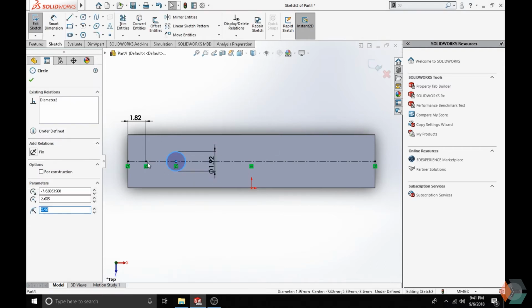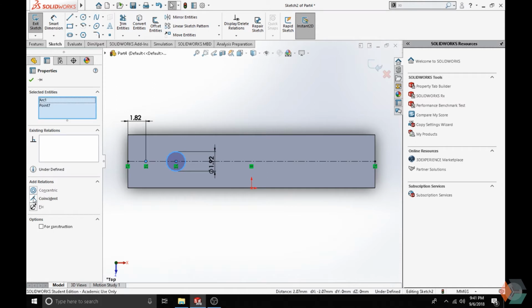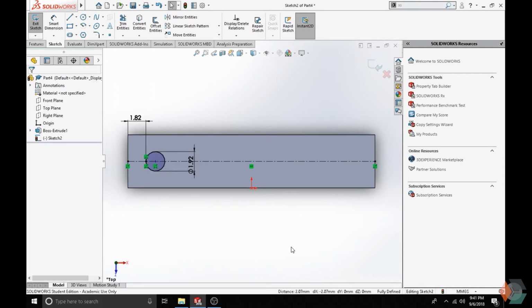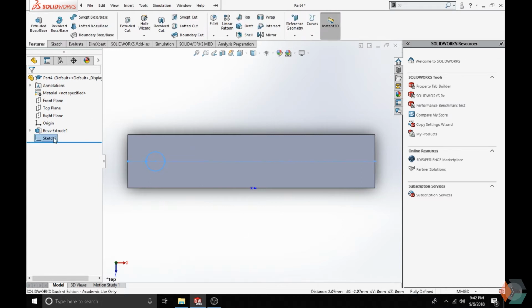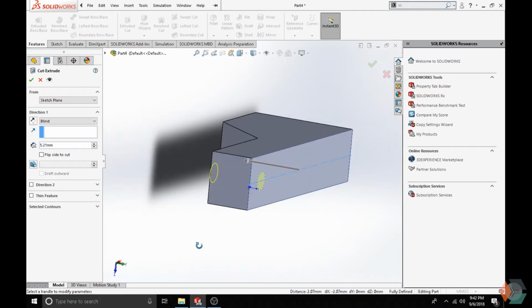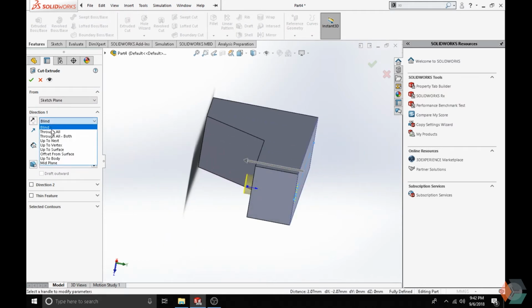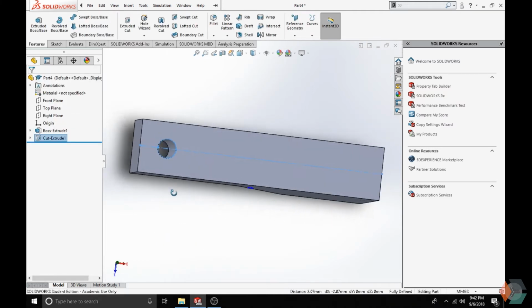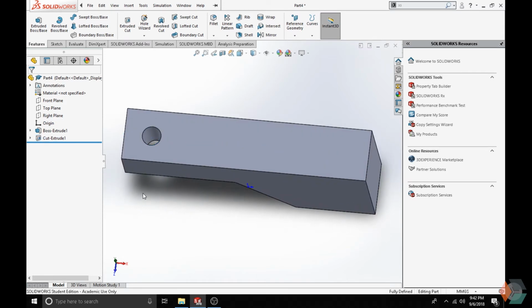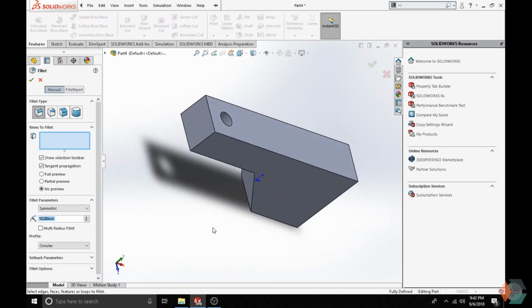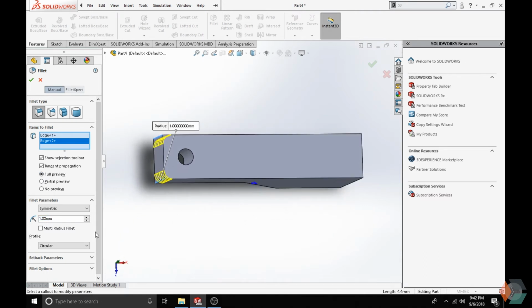Select that, select this dot right here, import the option. Then exit the sketch, select sketch tool, do extrude, cut, change the option to blind. Okay, over there. Now use the fillet tool to curve the side. So we're going to activate that similar to